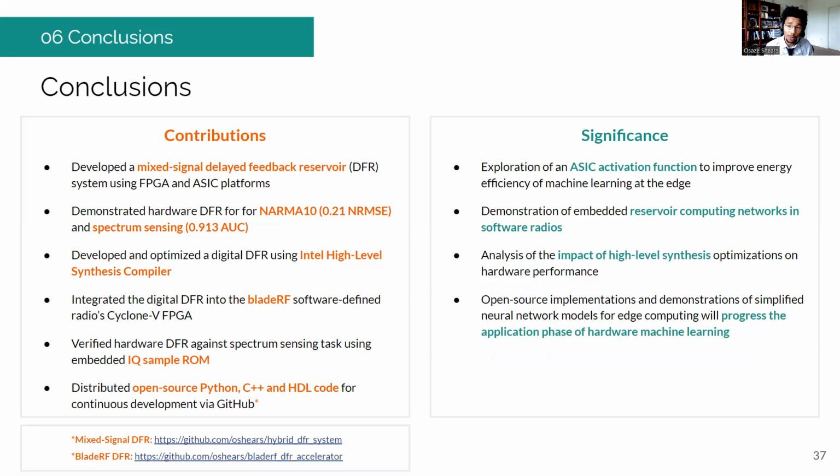In terms of the actual DSP utilization, I mostly left that up to Intel, the compiler, to decide, but there are switches inside of the high-level synthesis compiler that you can use to manipulate to which degree it's using those DSP blocks versus the actual lookup table logic, the programmable logic.